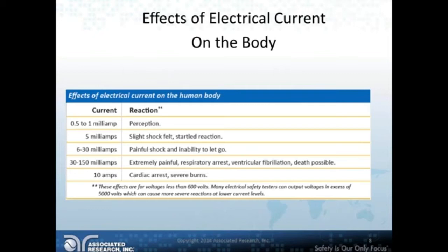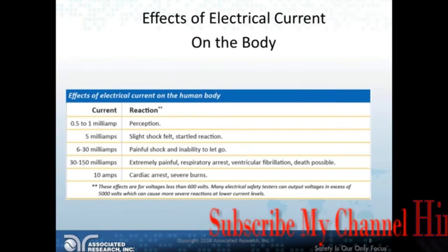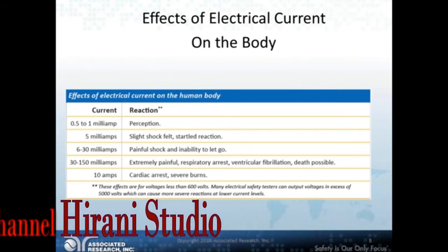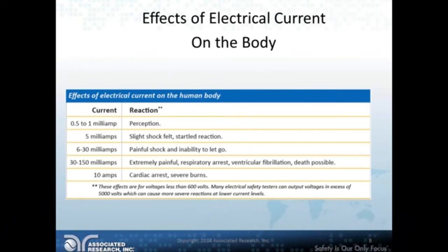At 5 milliamps, you could have a slight shock felt, and at that point you could have what we would call a startled reaction. I'm sure many people listening to this, myself included, have accidentally, at home, while messing with something electrical, plugging something in, had a finger come in contact with the live blade of a plug. You get a little zap, and it gives you that little startled reaction. That in and of itself might not be very dangerous, unless you have a pacemaker or something along those lines.